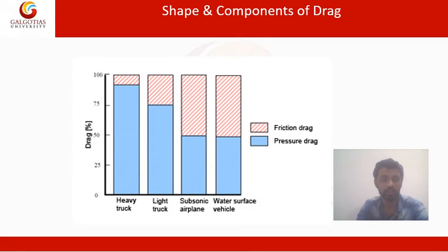And the wave drag will occur either when a solid object is moving through a gas at or near the speed of sound, or when a solid object is moving along a fluid boundary, as in surface waves. So drag, remember this, always depends upon the properties of the fluid and also on the shape, size and speed of the object.